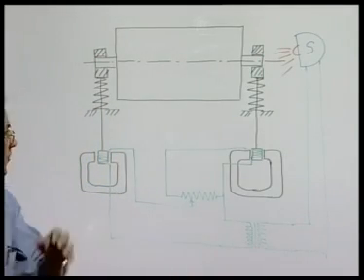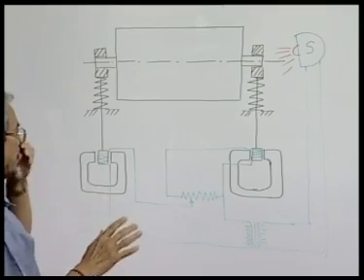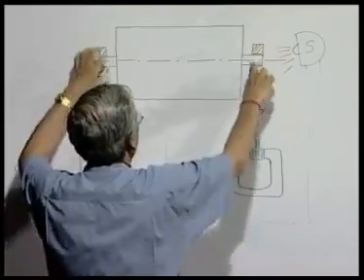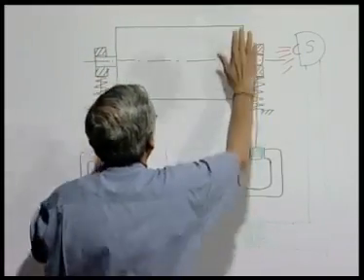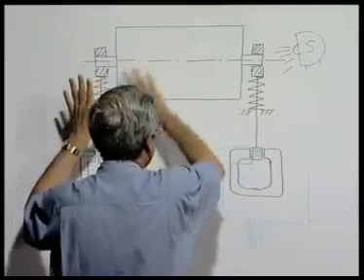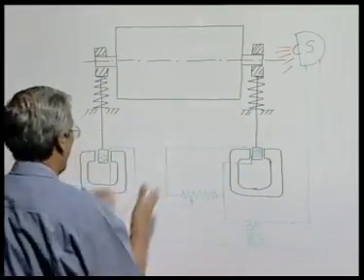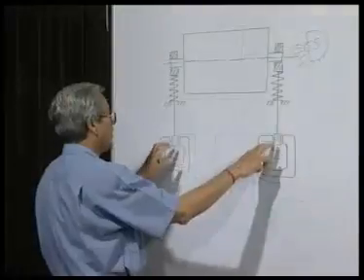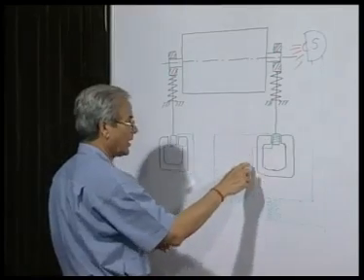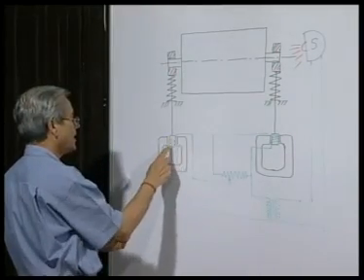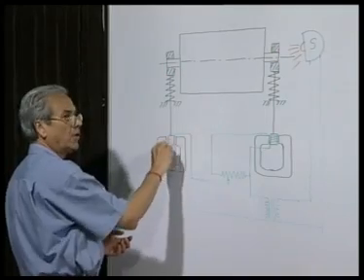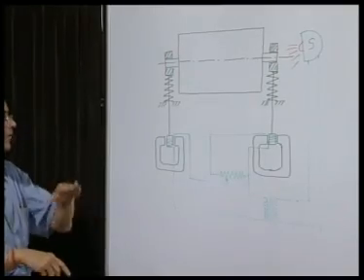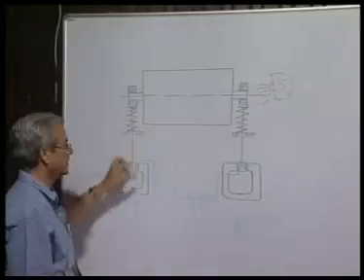So, first let us understand the whole setup, as I was mentioning. These bearings which can move up and down supported by springs, either up and down or to and fro. Actually the whole thing may be in a horizontal plane or maybe a vertical plane. Then these solenoids also move up and down here. These are the electromagnets or rather permanent magnets. Then the coils here will generate, depending on this motion, some voltage.